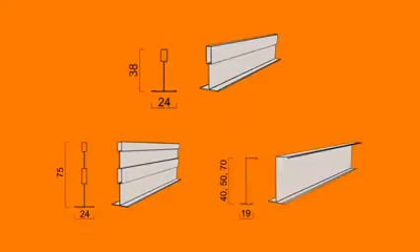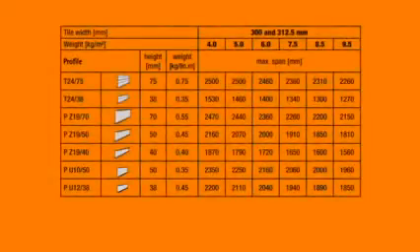You can find the appropriate maximum span table online at www.amf-grafenau.de. The installation of the next tiles follows in rows, always with the corresponding reinforcement profile. No tile may be installed without a reinforcement profile. The individual tiles should only be gently pressed against one another without too much effort. This makes it easy to remove the tiles in the future.